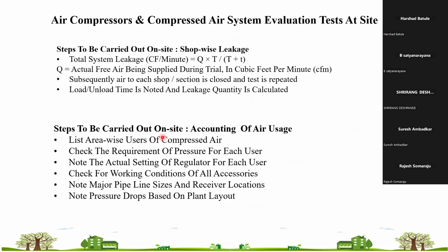Okay, but we have to compare it to the standard FAD of the compressor, and the deterioration over the period of usage. Yes. That comparison will help us conclude how much wear and tear and internal leakage is there. You're right.